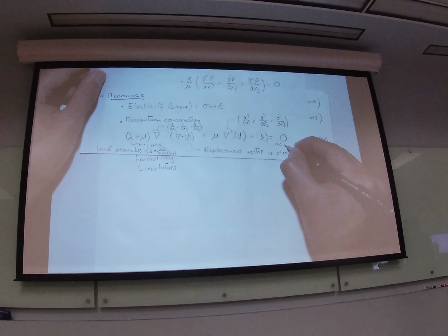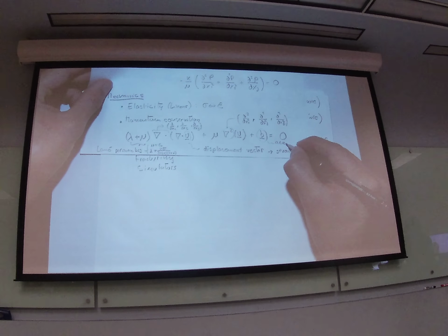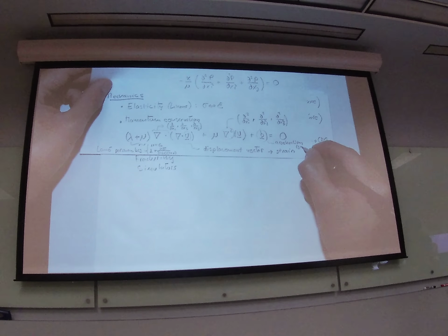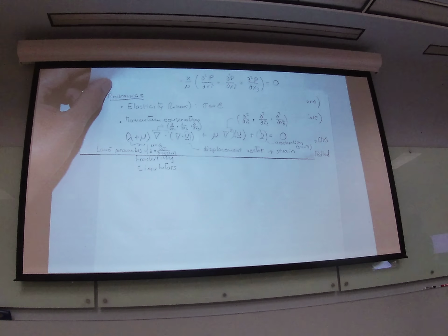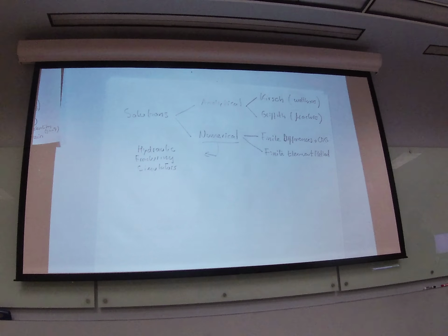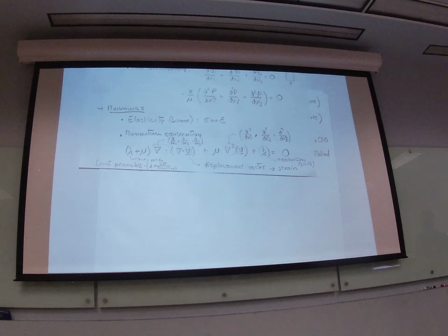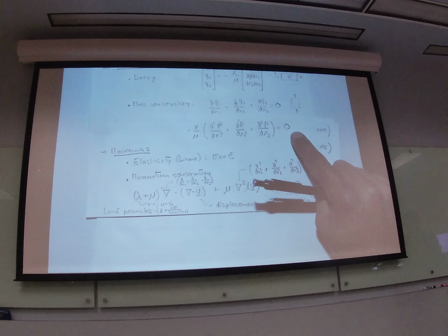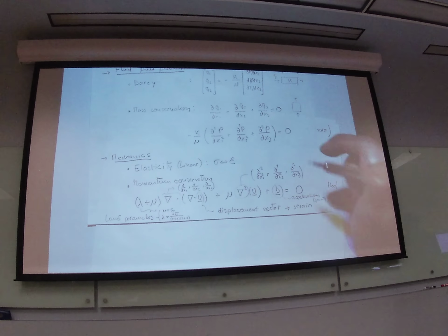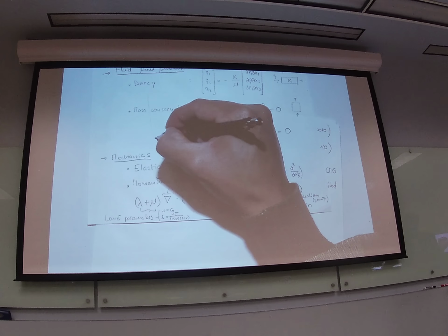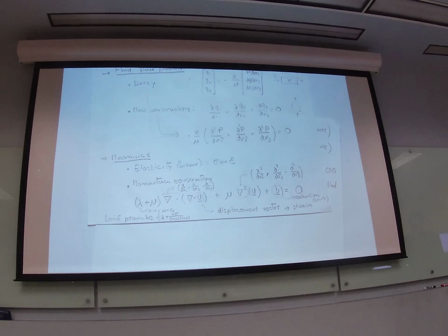This is the acceleration term, which in most cases is just gravity. So we have this displacement equation, and then we have the diffusivity equation, obtained by combining Darcy's law and continuity. Yes, this equation. So you put these two together, and then you get this one.